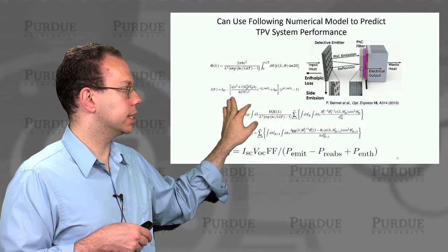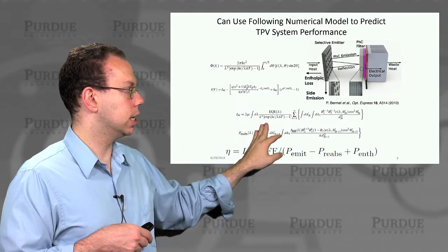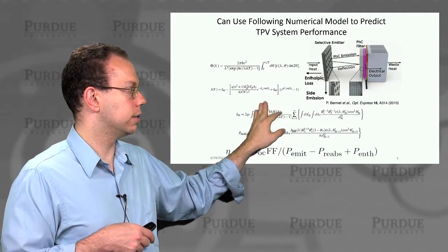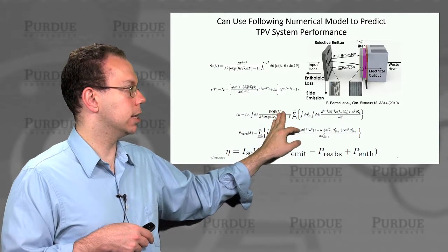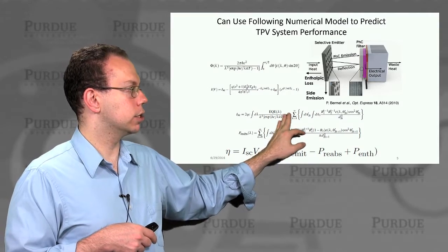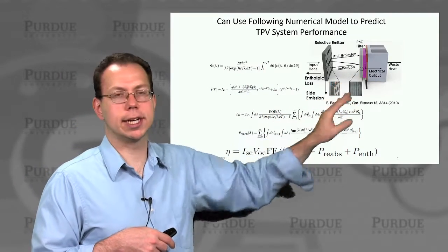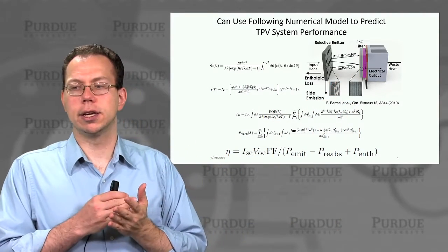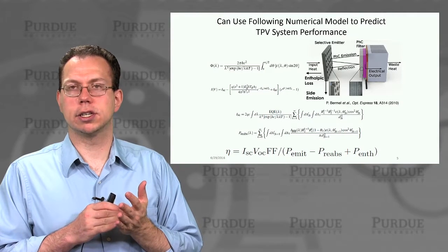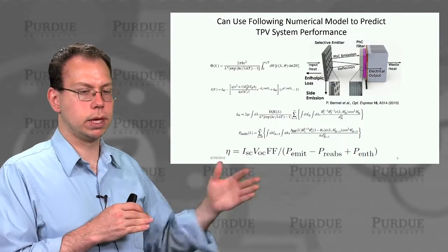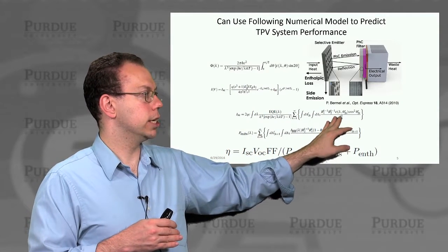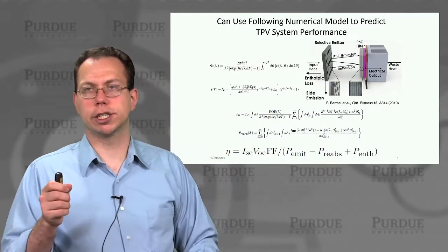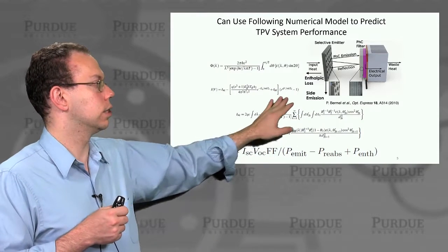And so this ISC is what determines the emission property. So that's the first term of the current voltage relationship. And this depends on the emission times this external quantum efficiency for the photovoltaic cell. Of course, any wavelength that's too long would essentially have EQE of 0. And then times both the direct absorption as well as any multiple reflection absorption, which is shown here.